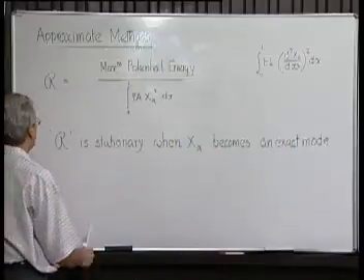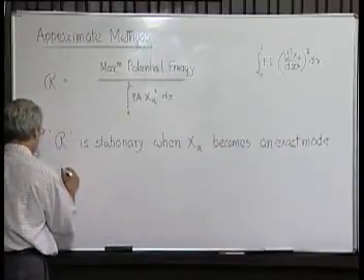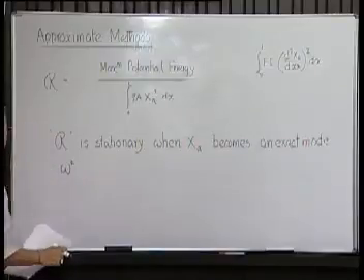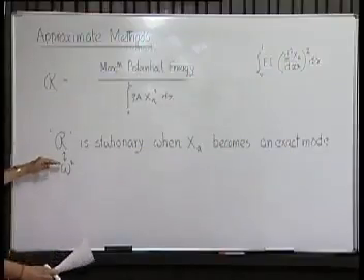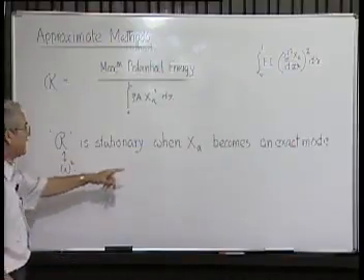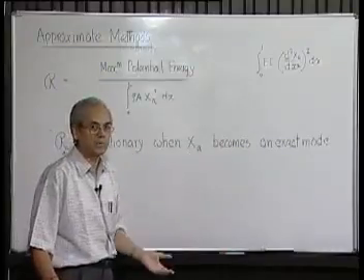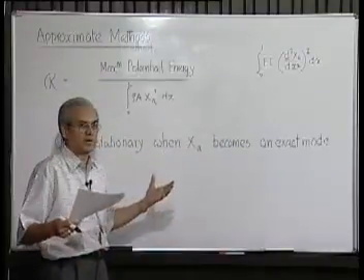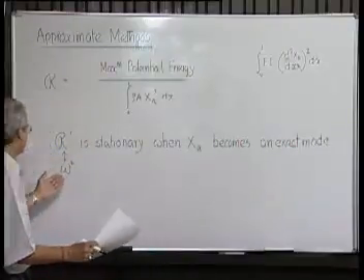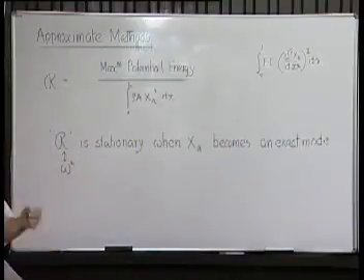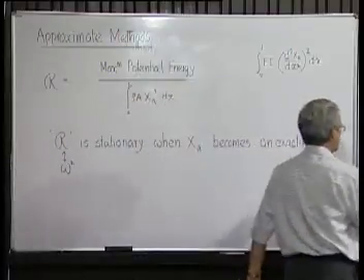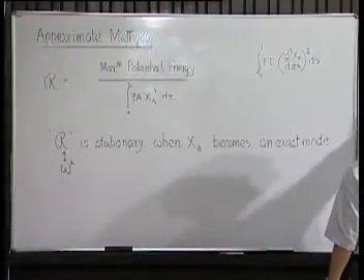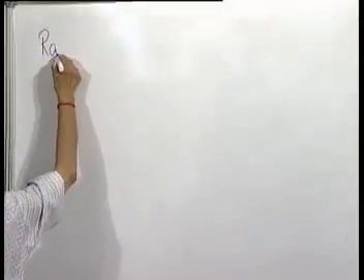So therefore, the omega square that we will get, which we associate with this, will become lower and lower as X becomes a better and better approximation, and when X becomes indistinguishable from the exact mode, then the real natural frequency will be the lowest. So this property of Rayleigh's quotient is used, and this proposal was first suggested by Ritz, and the whole process is therefore called the Rayleigh-Ritz approach.